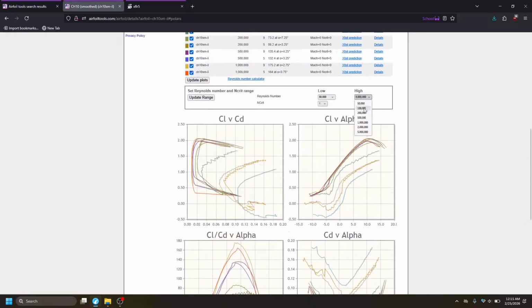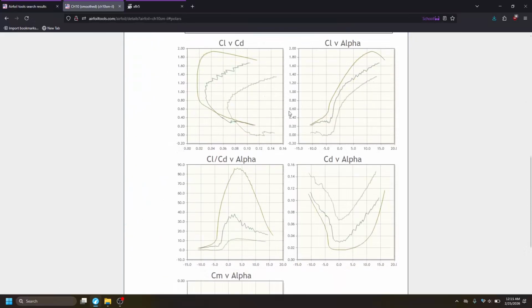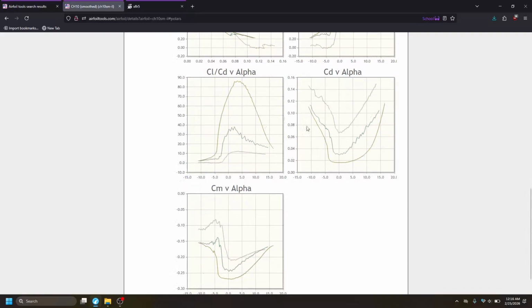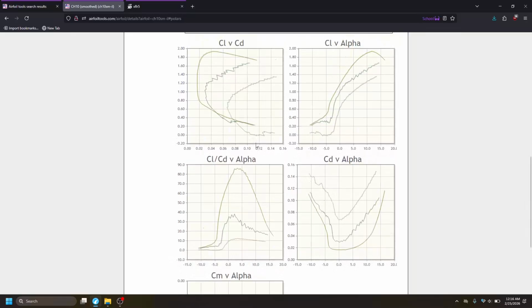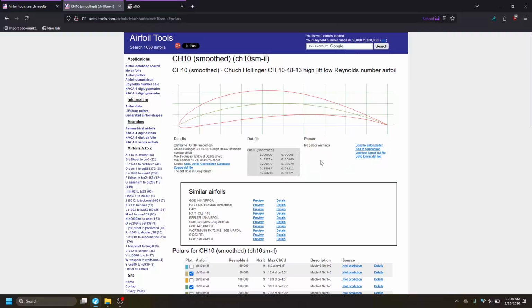Now, because we're going to be operating in air, which is not very viscous, we're going to be operating at low speeds, and that's going to tend to be more turbulent. This is more of the range we're going to expect our flow to be in. And so you can get a good gist of what the airfoil is like. If you were to run a single element, you can do this 2D simulation and compare your values to these values here from XFoil, and then be able to understand, is my STAR working well? That's not going to be the purpose of this lab, but we can do another one later on.